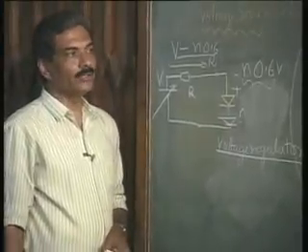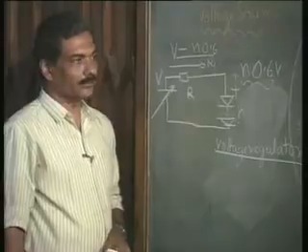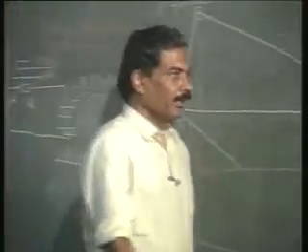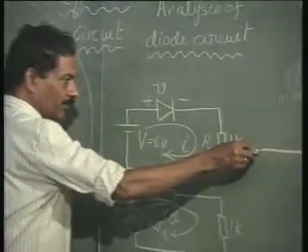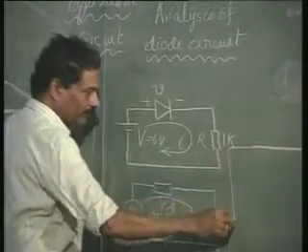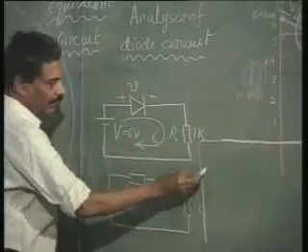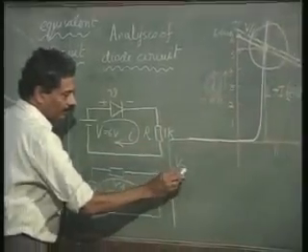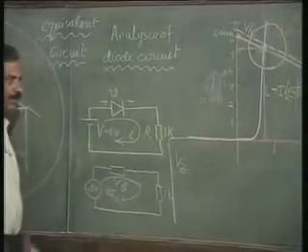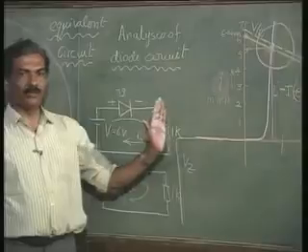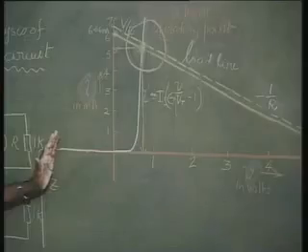or I can use what is called a Zener diode. The diode we have seen breaks down at a certain point, this characteristic we have seen. This is called the Zener voltage Vz. Under normal circumstances, this has to be greater than the peak reverse voltage that is coming across the diode.